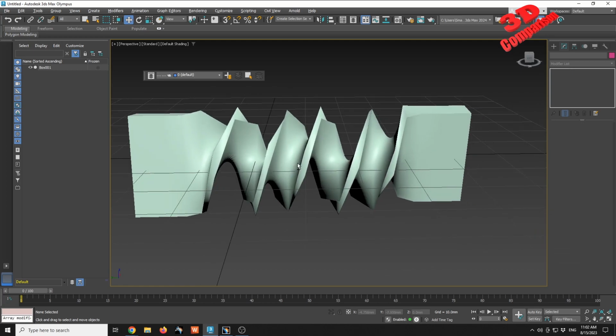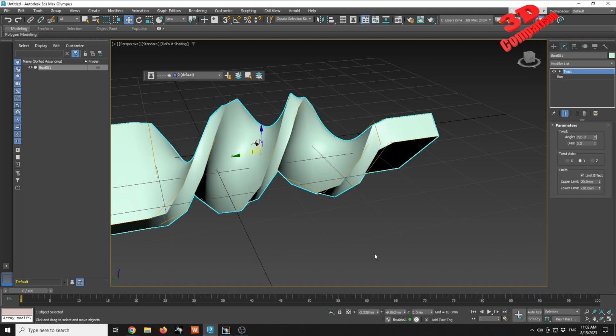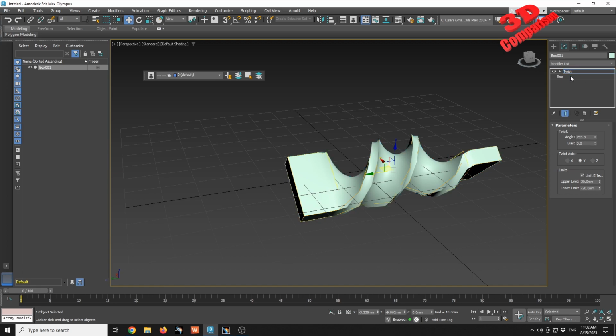But keep in mind that if some parts are quite small and you're gonna twist them a lot, they will heavily deform. So something like this with 720 degrees should be more than fine for a part that only has 65 millimeters. And also it's important the ratio over here, and with the ratio we see with a width and height of 20 and 5.